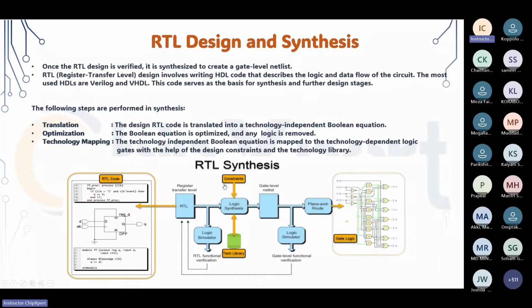And next, the RTL synthesis. Here, in the RTL, we define the logic, but it is not completely the logic circuit. It has the basic understanding of the circuit, which will be redefined with all the logic gates, with all the constraints for each and every gate. This is how the design goes from RTL into the gate level netlist.